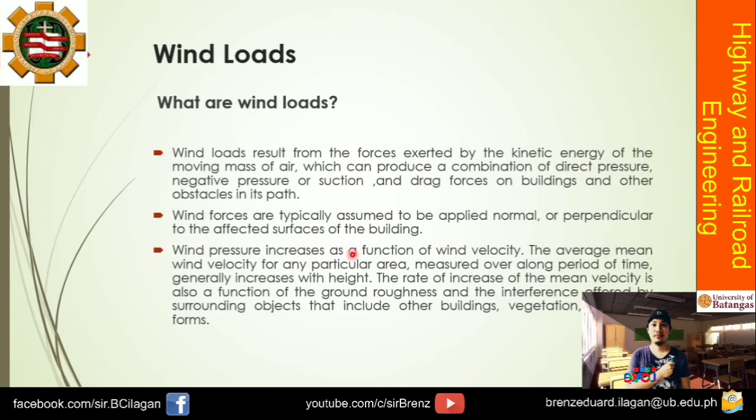Wind pressure increases as a function of wind velocity. The average mean wind velocity for any particular area, measured over a long period of time, generally increases with height. Okay, so habang tumataas pala, mas malaki yung wind pressure na nangyayari dun sa iyong structure. The rate of increase of the mean velocity is also a function of the ground roughness and the interference offered by surrounding objects that include other buildings, vegetation, and landforms.